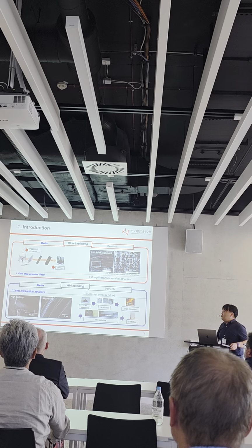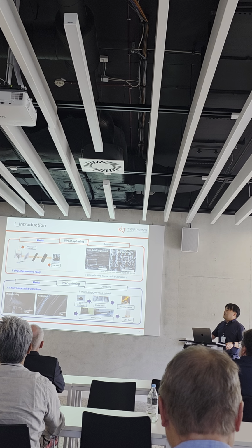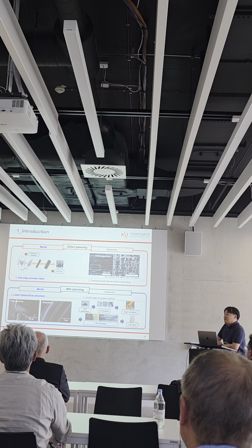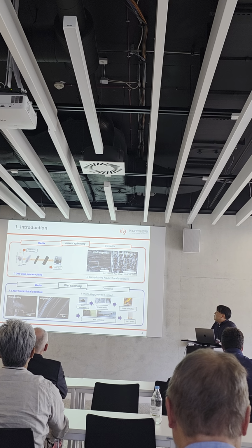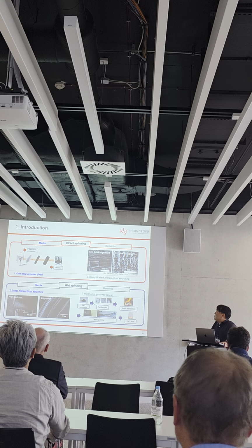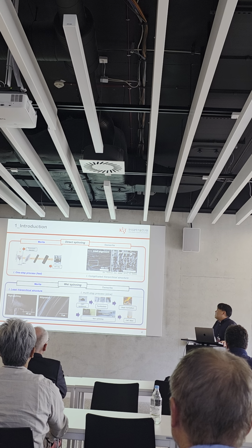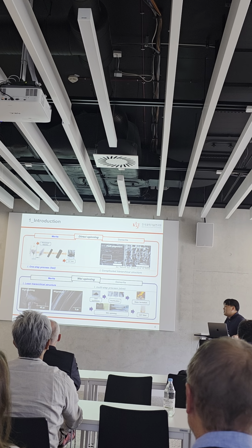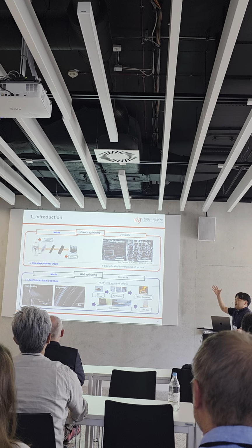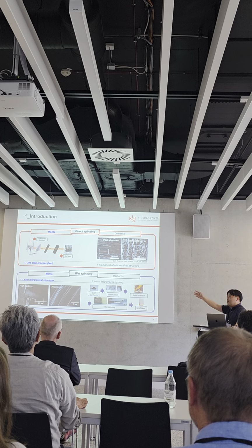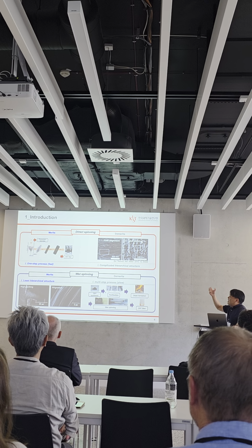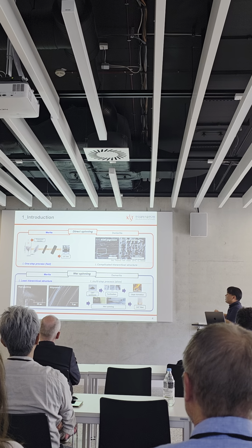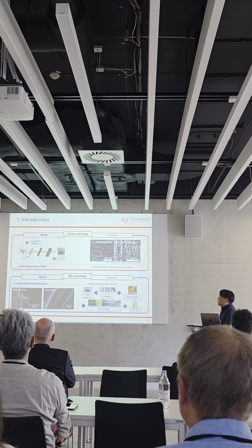There are usually two ways to fabricate the CNT fiber. One is direct spinning, which was developed at Cambridge. Basically, there's a reactor under some conditions, based on the floating catalyst CVD method, and under specific conditions it forms a sock of CNT, and then it densifies in water or another liquid, and directly forms the fiber.